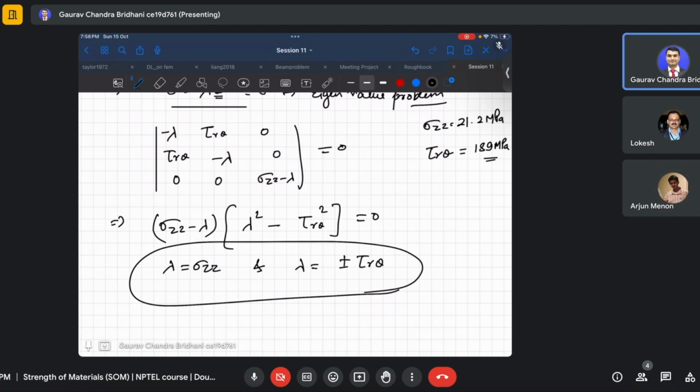Yeah, so for bending it will be in a different way. But you have to just remember the system. If you are using Cartesian, then use Cartesian for both torsion and bending. The thing is, one is being derived in Cartesian and one is being derived in polar coordinates, so that makes it a little bit problematic. That's all.